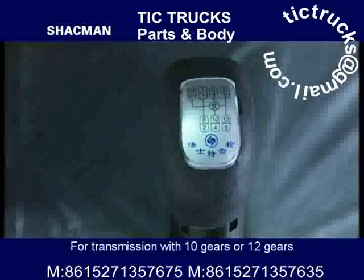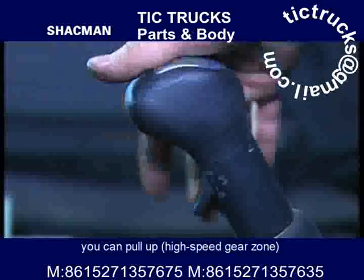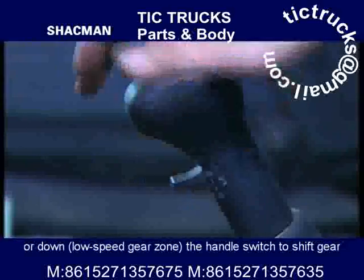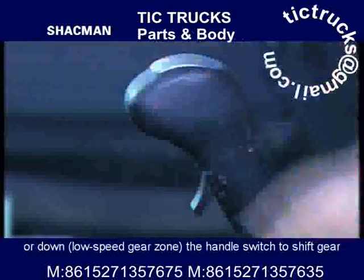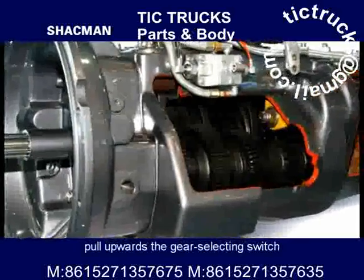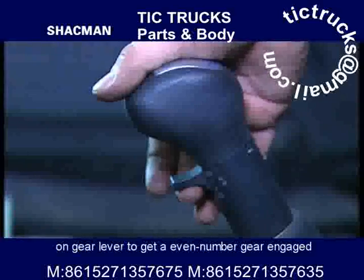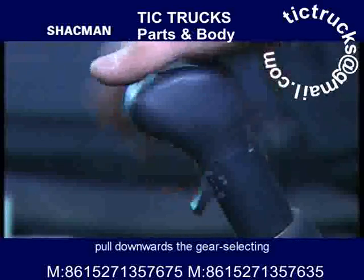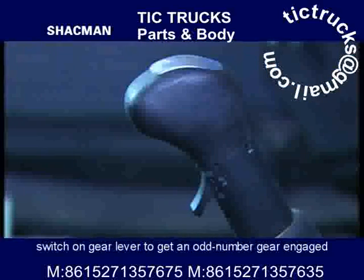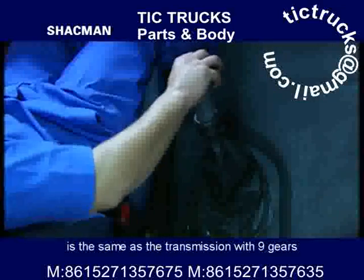For transmission with 10 gears or 12 gears, you can pull up to the high-speed gear zone or down to the low-speed gear zone with the handle switch to shift gear. For transmission with 16 gears, pull upwards the gear selecting switch on the gear lever to get an even number gear engaged. Pull downwards the gear selecting switch on the gear lever to get an odd number gear engaged. And the shifting between high and low speed gear zones is the same as the transmission with 9 gears.